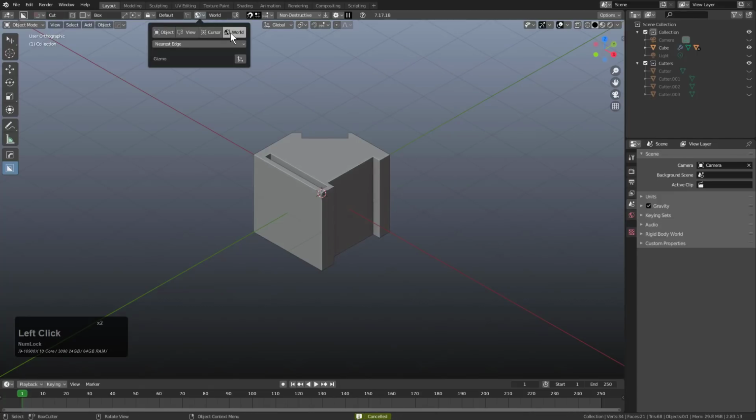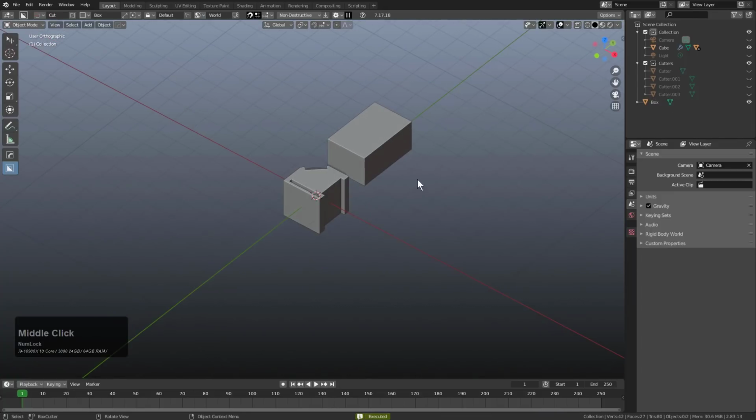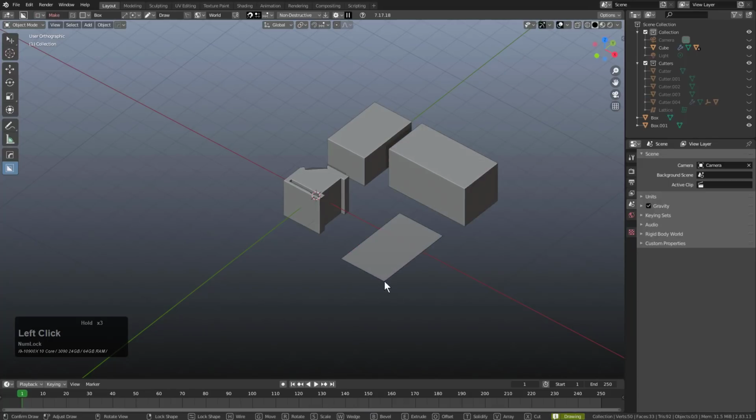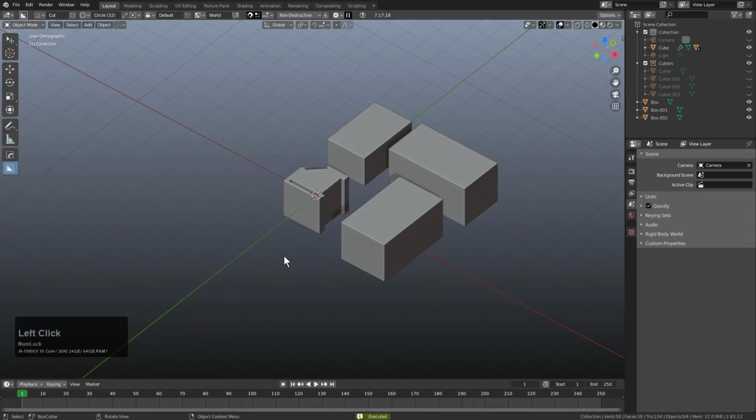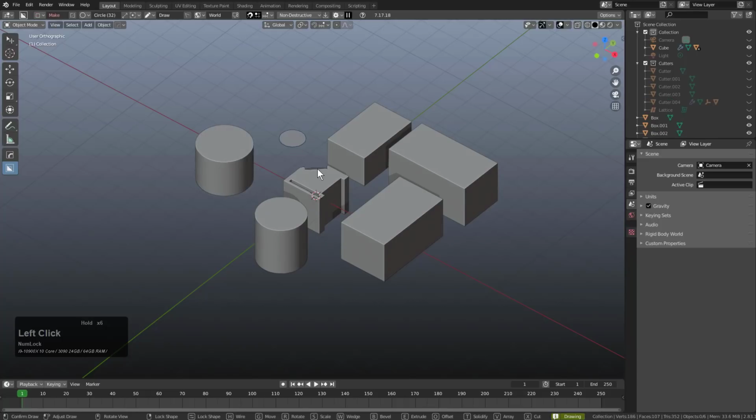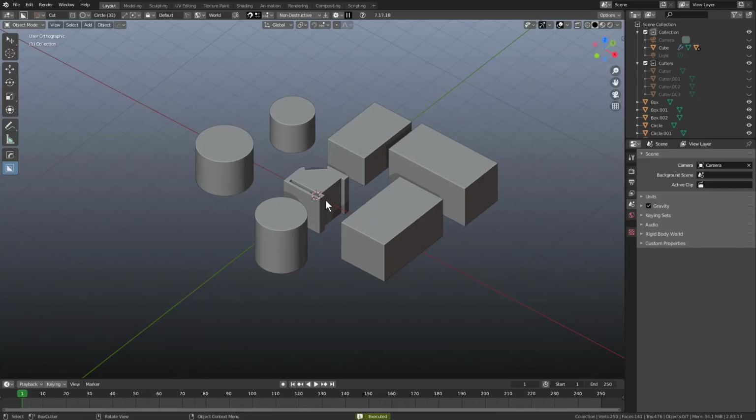In this case, my world is set to Y. I need to set it to Z, but once you have your world set to Z, you can begin drawing on the ground floor of your world, just begin creating shapes without any issue, jump through all the shapes and just create shapes on the fly without any issue whenever you're using make, because nothing is selected and we have our world set to Z.